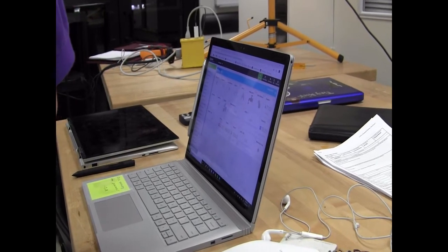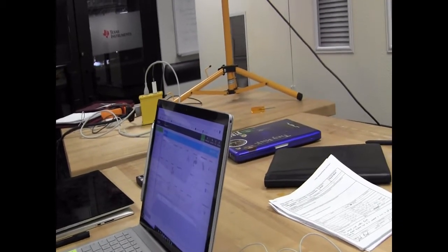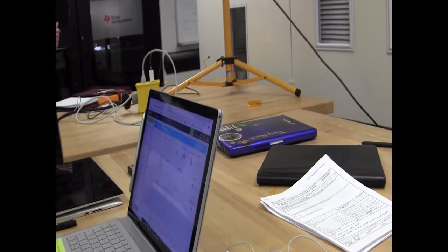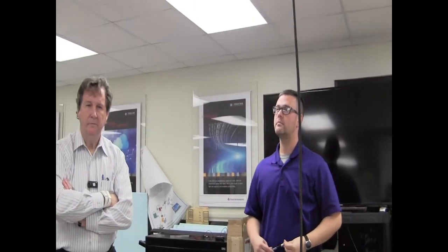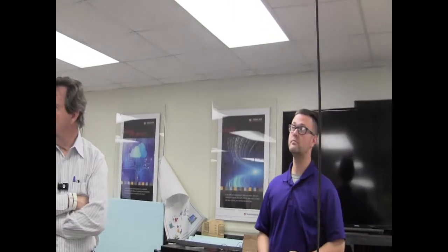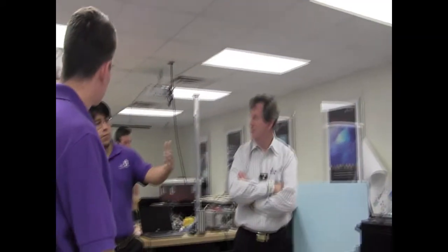Are you sending the analog value or a digital value? We send an analog value to the CC3200, and in order to meet the needs of the ADC, we cut it in half. So instead of 3.3 volts max coming back, we cut that down to 1.6-ish. But what are you sending to Cayenne? Are you sending a digital or an analog value? As soon as it passes the analog threshold for being submerged in water, we send a binary value indicating whether it is submerged.